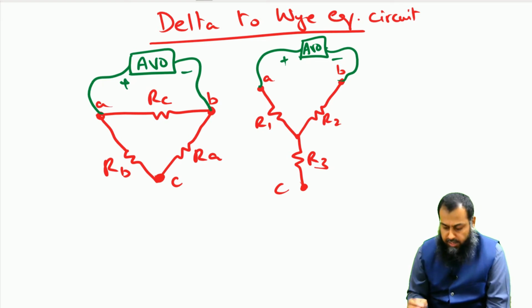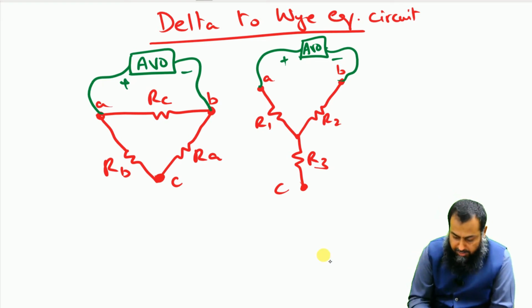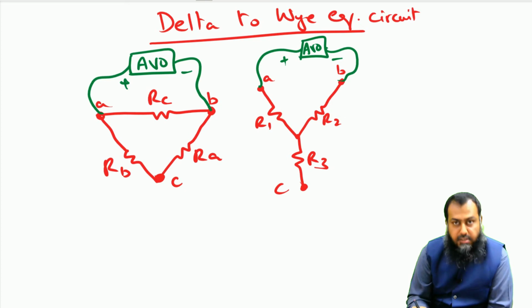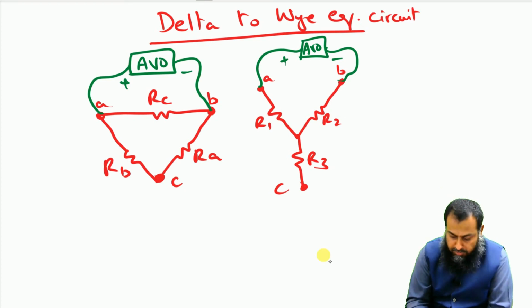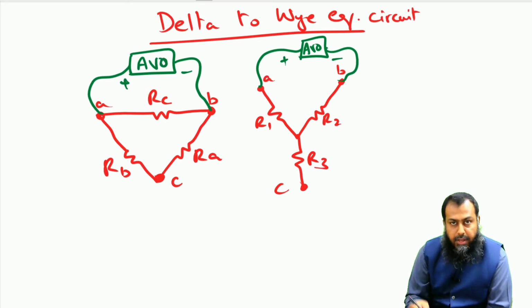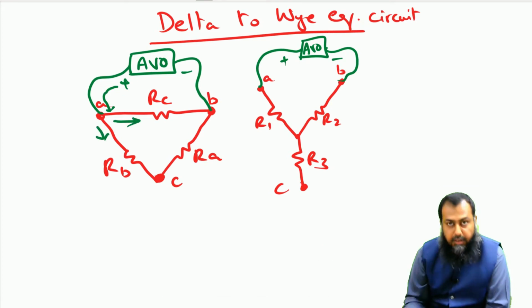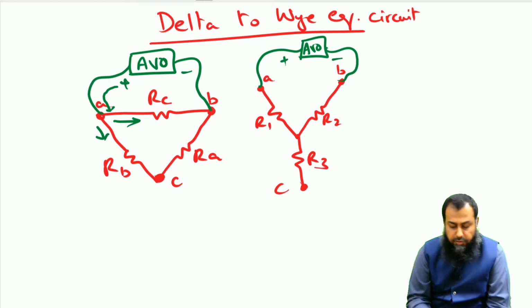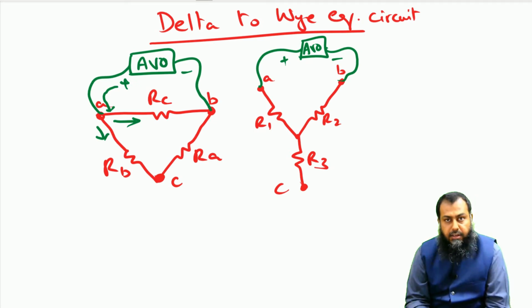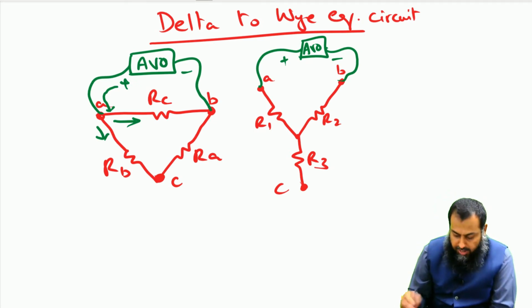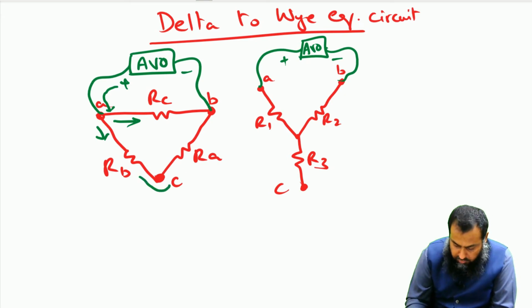So, if I apply this meter to measure the total resistance here, then because of the operation of the avometer, a small current will flow and it will come into this junction A, and it will divide into these two branches. Thereafter, consequently applying Kirchhoff's current law at this node, this current goes through this RA, and then they combine at this node B and go back to this avometer.